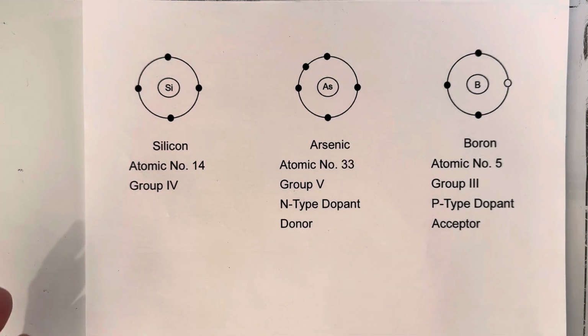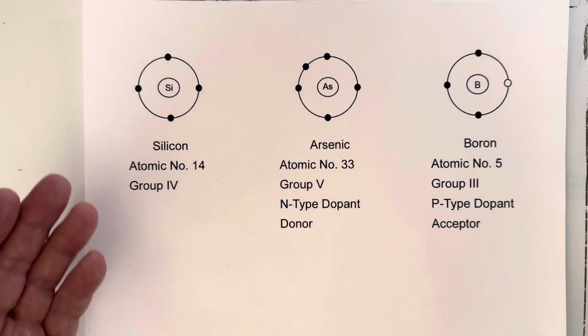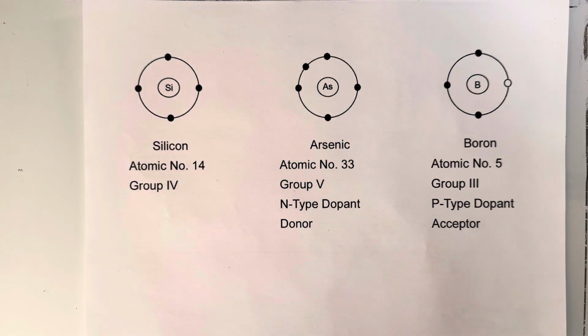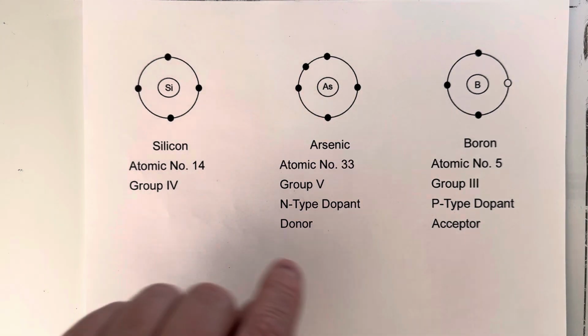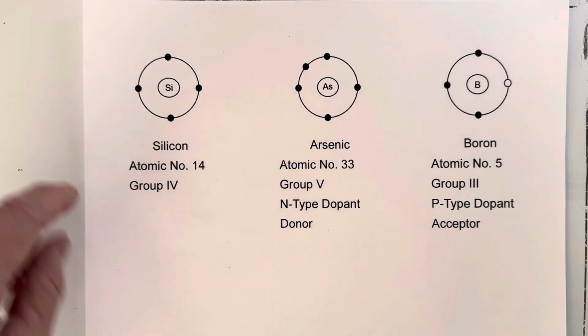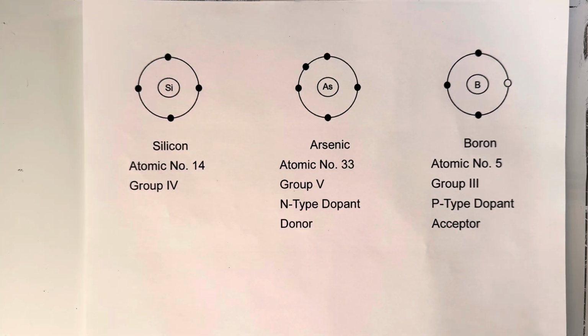This is the main semiconductor material used today, and it's, as you can see, atomic number 14. That means it has 14 protons in the nucleus. And it's also going to have 14 electrons orbiting around it. Now, in this view, I'm condensing all of the inner electrons and the nucleus into this center circle marked Si for silicon. All we see orbiting around it are the valence electrons. Silicon has 4 valence electrons. Those are the electrons in the outermost shell.